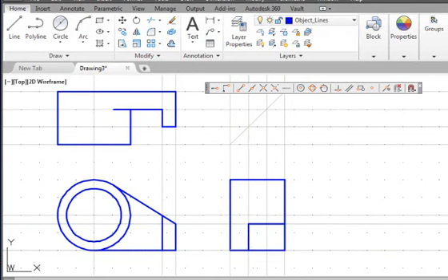We also have an inclined surface that is visible in the side view. The surface is also visible in the top view. So we will go to the top corner of the rectangular surface we just created and create the inclined surface. The last vertical line needs to stop at the tangency point, which can be located by projecting from the front view. On the rectangular surface, we have a hole feature. To draw the circle, we can create additional construction lines or use the Snap From option available in the Object Snap toolbar. Activate the Center Diameter Circle command.